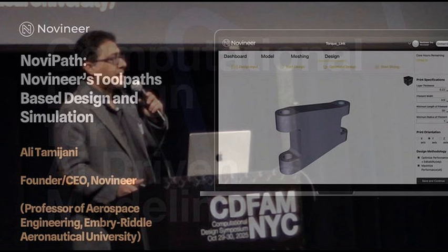So the first thing we did was the coupon testing, right? So you have this path, you have multiple materials, so it's not about one material. You still have filaments, but filaments related to different materials. And so you have different material properties in different sections. And here you can see the computational and experimental results, published probably five, six years ago. And you see 223 megapascal versus 226, so close enough.